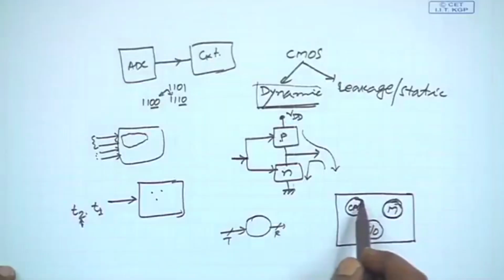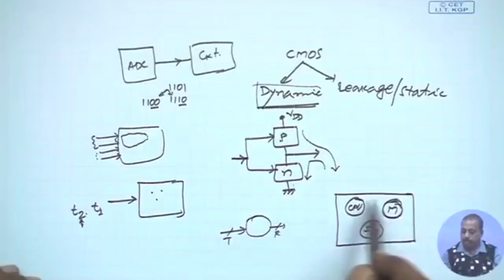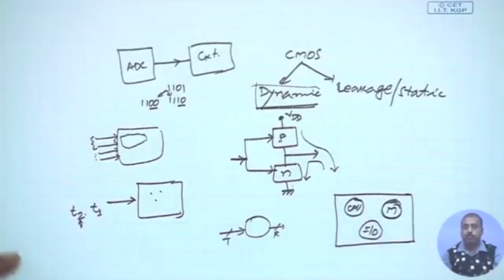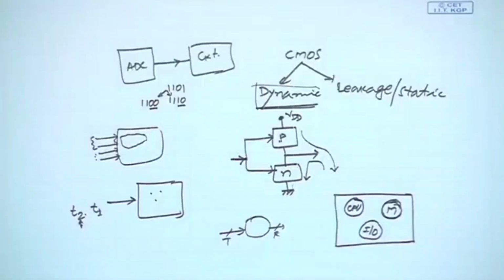But in this particular situation, we have got only a soft description of the CPU in terms of netlist from the vendor, and we are combining them into one, and on a silicon floor we are going to manufacture them. Even if my manufacturing process is 100% correct, there may be impurities in the silicon. No silicon is 100% pure. As a result, the CPU might not have been fabricated properly. So, I need to test the CPU even if my manufacturing process is 100% correct. That way this testing is required.